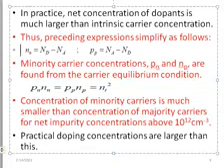So in practical doping, whether introducing group 5 or group 3, the concentrations are much larger than this. So in that case, if you introduce much of group 5, electrons dominate everything, though we have holes as minority. If you introduce much of group 3, the holes will dominate, even though we have some electrons as the minority charge carriers.